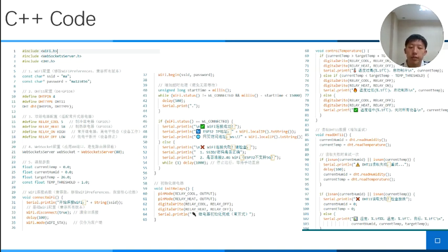The callback function onCMD received is responsible for receiving control commands forwarded by the cloud and forwarding them to the actuator through the serial ports, so as to realize the switch control of the LED light.